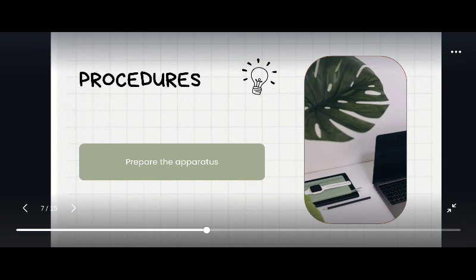Take out the bottle from water bath. Wipe it clean and dry it from outside. If the capillary of the stopper is not full, fill it with drop of distilled water. Make sure the bottle and stopper are clean and dry. Weigh the bottle filled with water and soil sample with stopper. Record the mass M3. Empty the bottle and clean it properly.